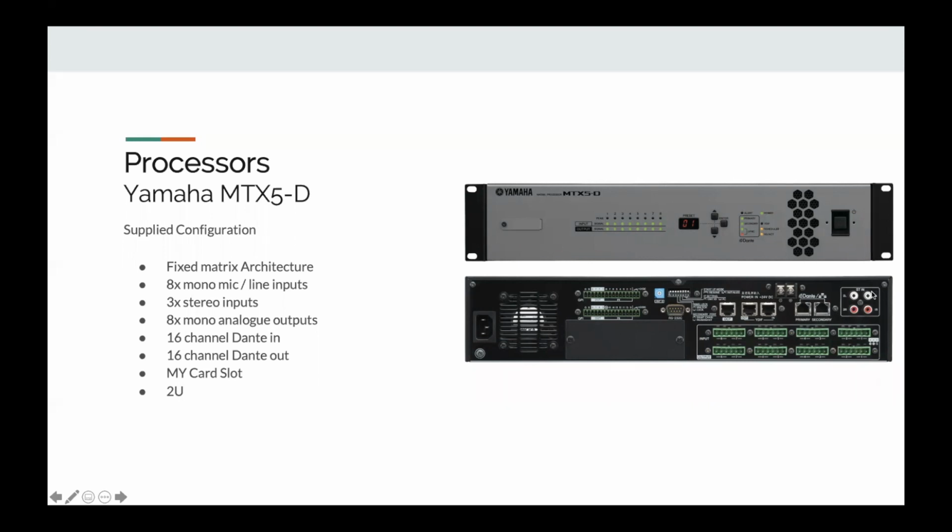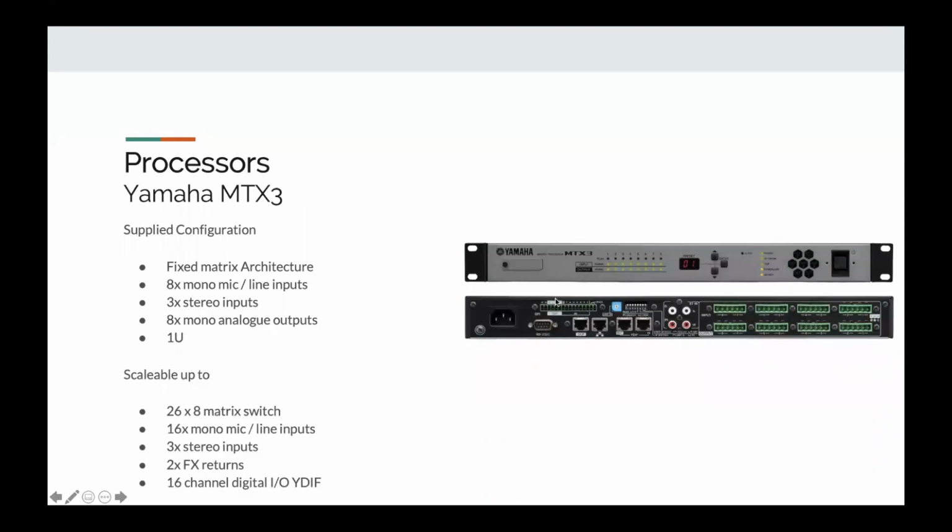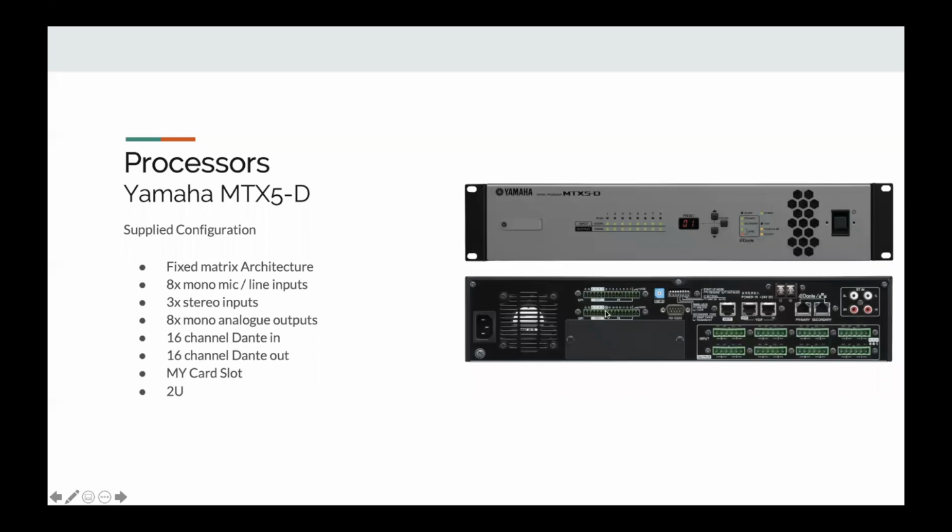Like the MTX3, you still have 2 sets of stereo inputs. You also have dip switches to configure how the device works. You can lock the device so that only certain functions are available from the front, or none. And the other thing, again, which I didn't show you on the MTX3, is that both the MTX3 and the MTX5 share a 16-pole connector over which you can use contact closure or rising high or falling low connections to trigger other devices.